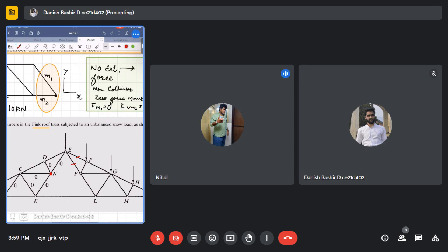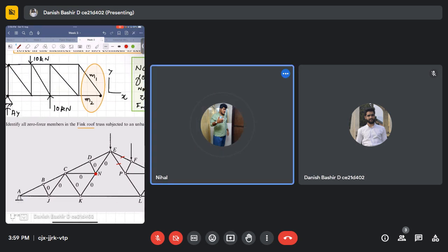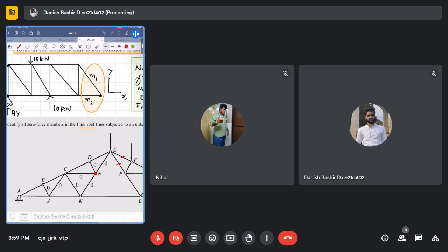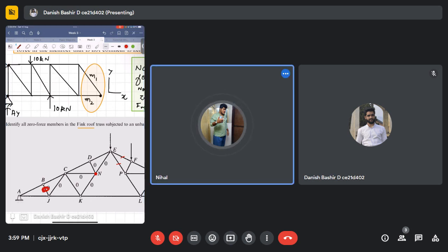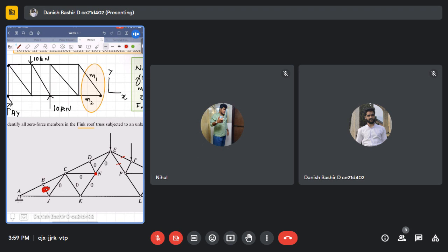Okay, sir, is this clear to you? Yes, sir. So look, here it was collinear, these were collinear, one is non-collinear, this comes to be a zero force member. Yeah, this is collinear, and once deleting this member, there are again three members. This is collinear, this is collinear.